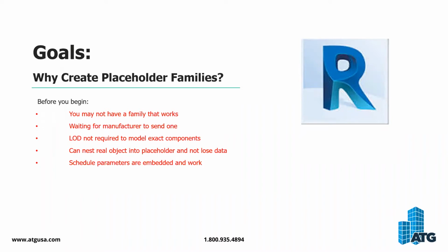If it's modeled as LOD 500 or better, but you only need the actual connection points, a placeholder family would be much better for that, just for the fact that you would not have, say, a 30 or 40 or 50 meg CAD file now embedded in your Revit model. And if that was done 3 or 4 or 5 times, model performance gets really, really bad when you have very large DWGs inside of Revit.